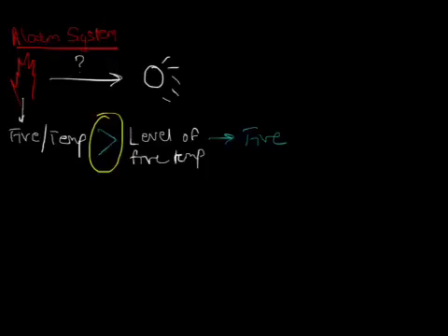Now, in real life, there is no way for us to check whether temperature is higher than a particular temperature unless there's a human out there. And we want to make this a machine without needing a human presence. So what we do, like almost every other problem, is convert the problem into another problem. We convert this fire or temperature into a voltage. We also convert this level into another voltage. And now our problem changes from measuring and comparing temperatures to measuring and comparing voltages.